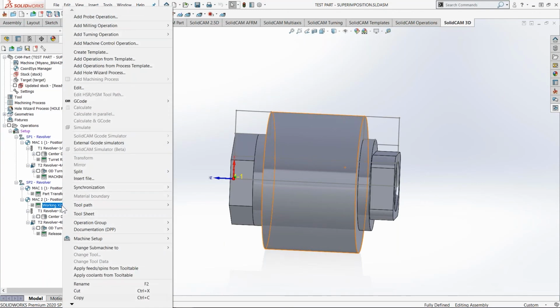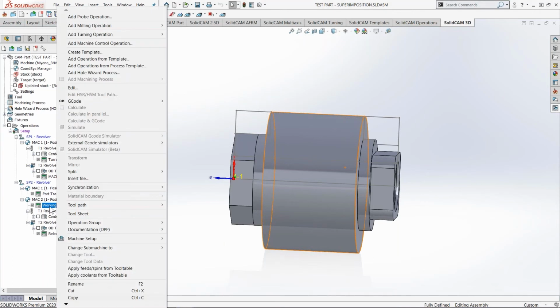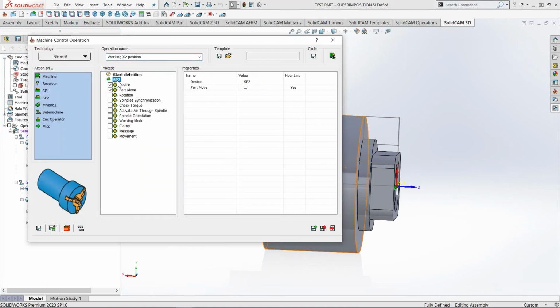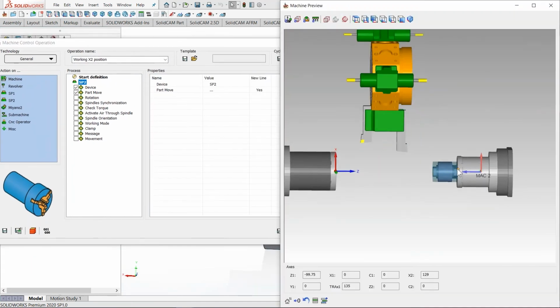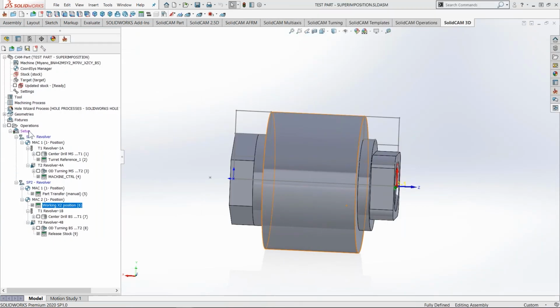This is interesting. MCO, basically nothing so special. We'll just move the part to be aligned with the sub spindle. Sorry, with the main spindle. So we actually approach here and make proper movements, yes, because otherwise, if the part is located down where the home reference is, the turret cannot reach this part over here. Okay, so let me just very quickly go to the channel synchronization.